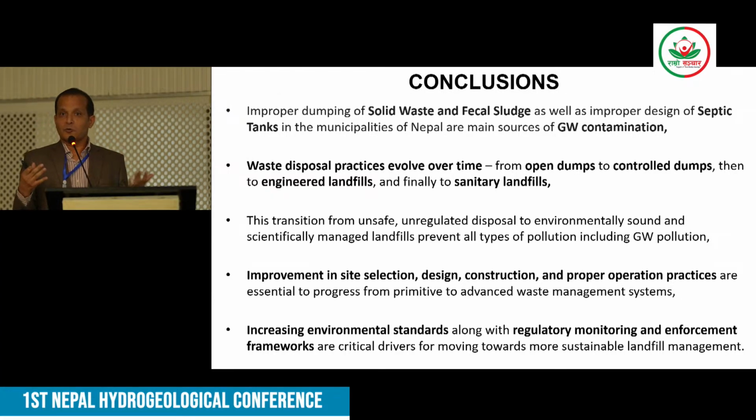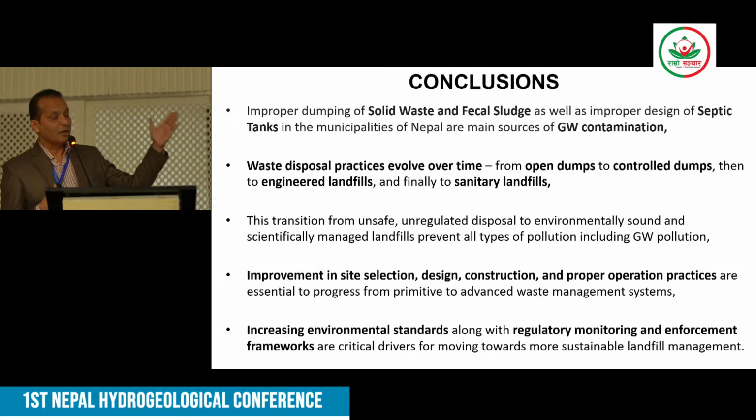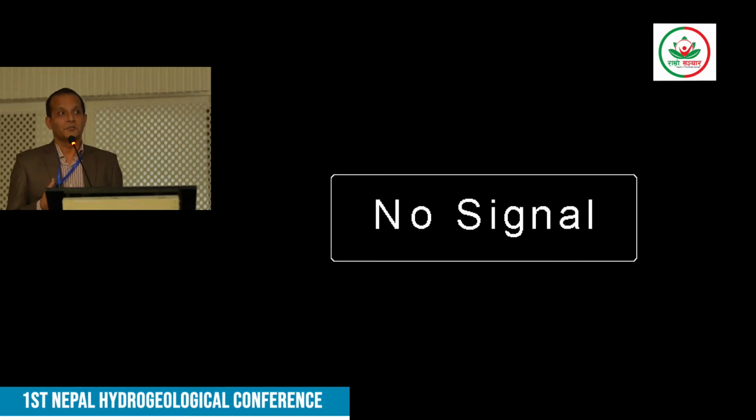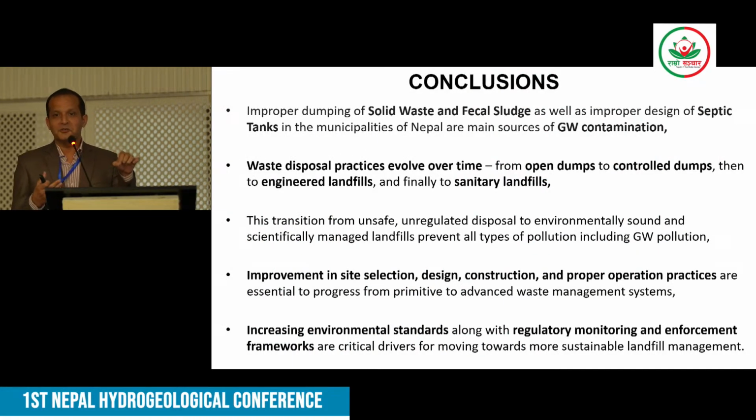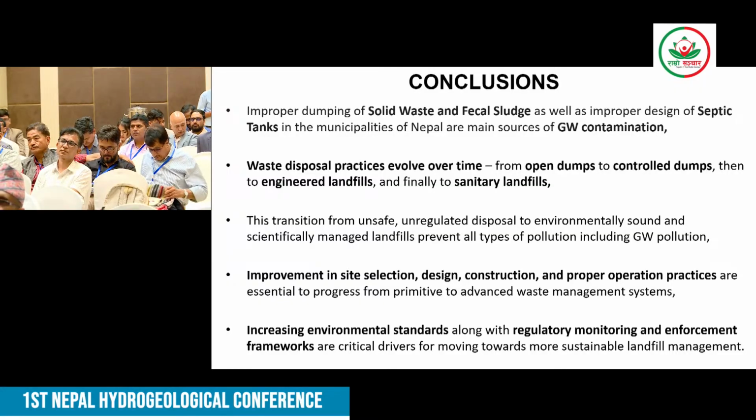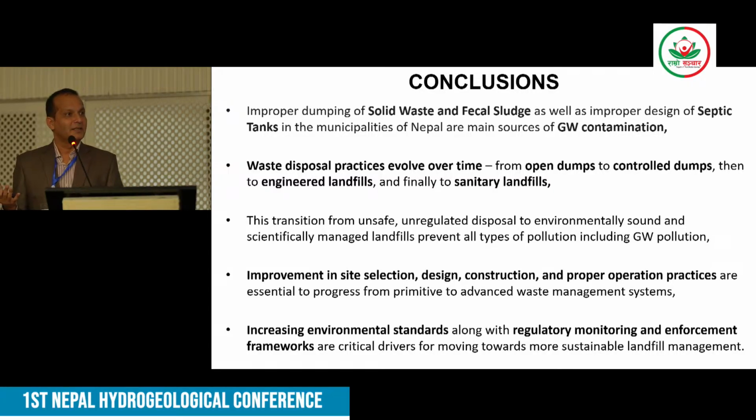But site selection and design are not the only important things. Another thing you have to think about is the operational practice also. Today's talk focuses on how to convert a dump site to an engineered landfill, through the combination of the knowledge of hydrogeologists, geotechnical engineers, soil scientists, and environmentalists. We started to do it, but finally we failed again because of poor operational practices. The good sanitary landfill ultimately converted to an open dump. That's why we have to work vice versa.